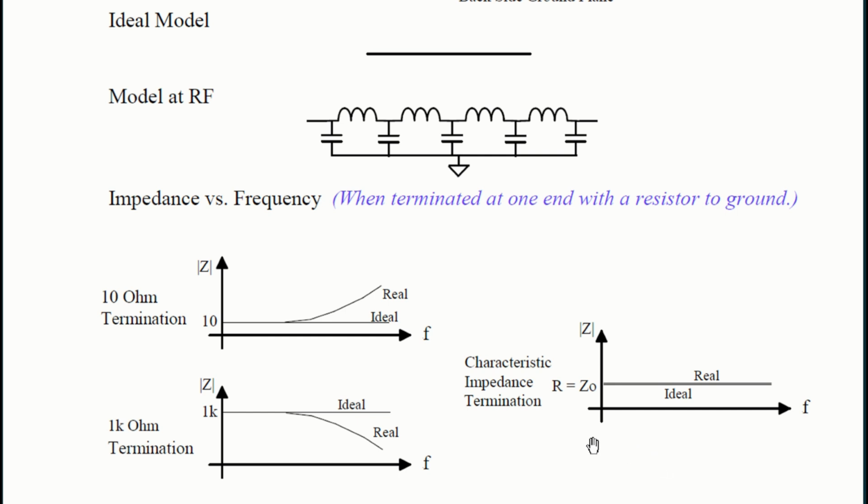Moving on, you may have heard about the characteristic impedance of transmission lines, coax or what have you. Here it is a microstrip trace on a circuit board. It has a characteristic impedance Z0, and if the terminating resistance is the same value as the so-called characteristic impedance of the line, then you could have the resistor at this end and look in this end, and magic happens. It's as simple as looking like the resistance again.